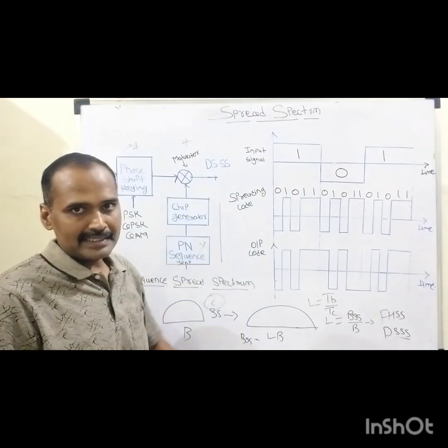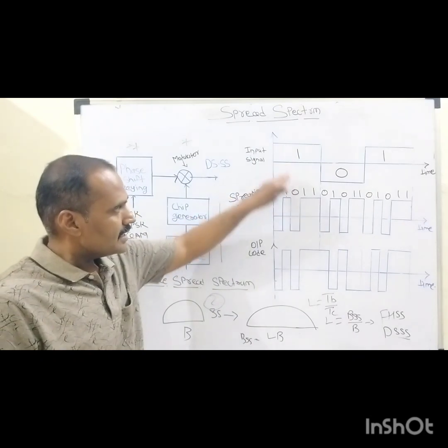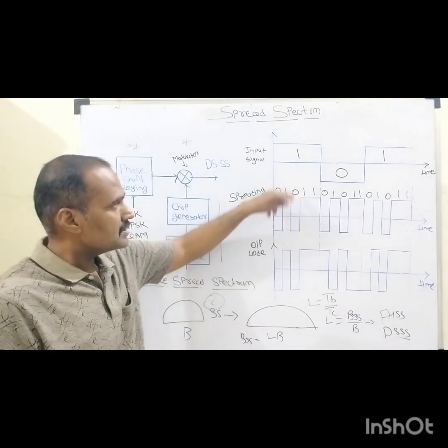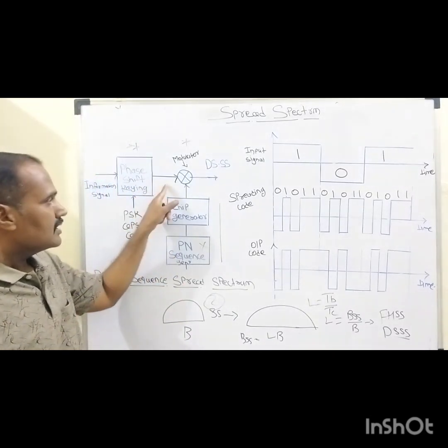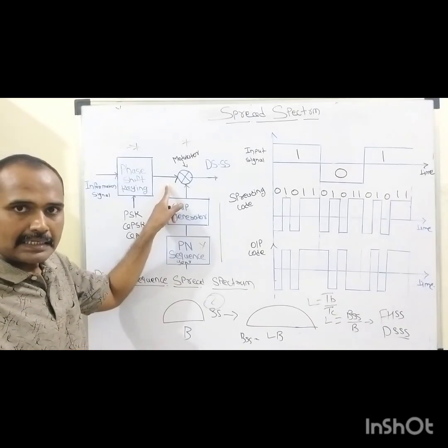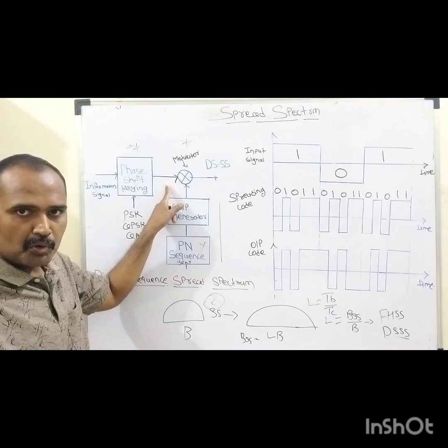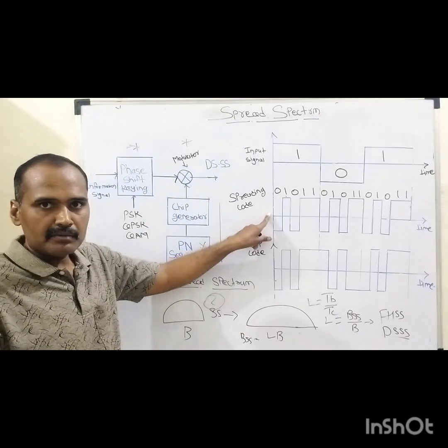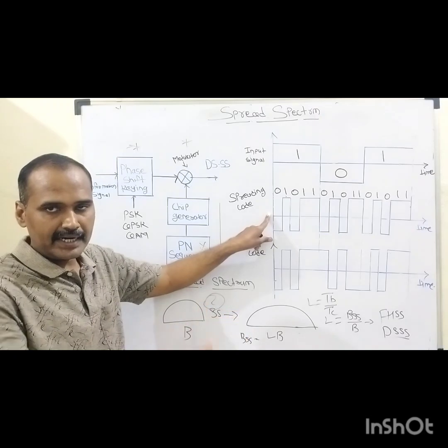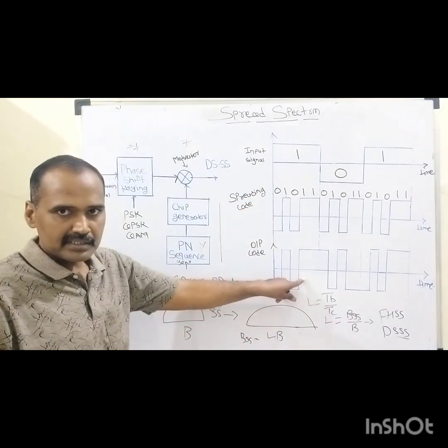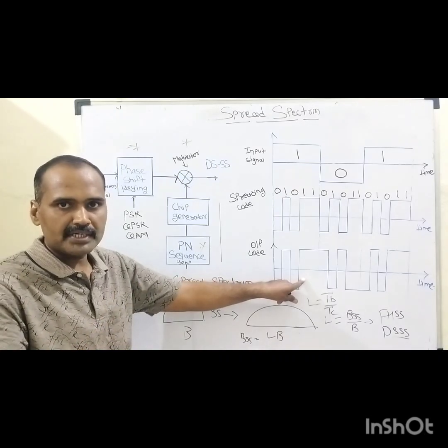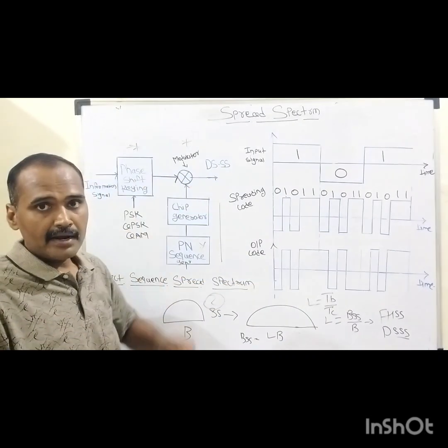Graphically, as you can see, during each signaling interval these two signals are multiplied with each other. Which two signals? The signals emitted by either the single carrier or multi-carrier continuous wave modulator, and the desired spreading sequence. In this way we generate the resultant signal to be transmitted by this DSSS transmitter.